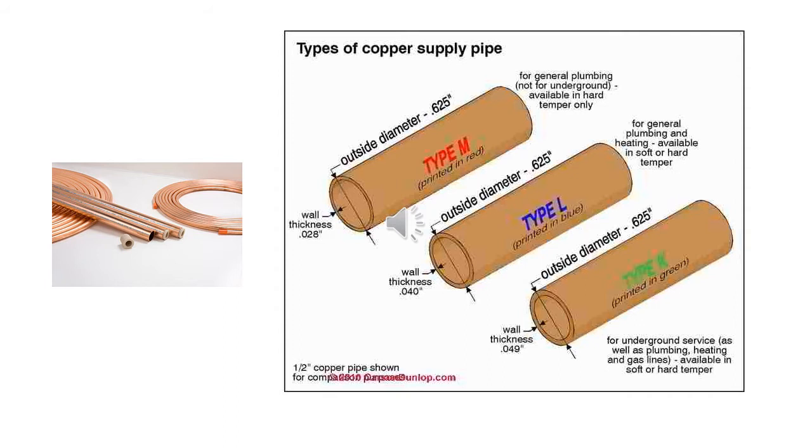When ordering copper tubing, you need to tell the supply house the type you want and the length you want. Hard-drawn pipe comes in 10-foot and 20-foot lengths. Soft copper tubing comes in rolls from 20-foot up to 100-foot. As an example, you want to order 5 20-foot lengths of 5/8 inch ACR and 5 20-foot lengths of ½ inch type M. You would tell the person how many and the length of pipe, the size, and then the type. So you would tell the person at the supply house, I need 5 20-foot lengths of 5/8 inch ACR and 5 20-foot lengths of ½ inch type M copper pipe.